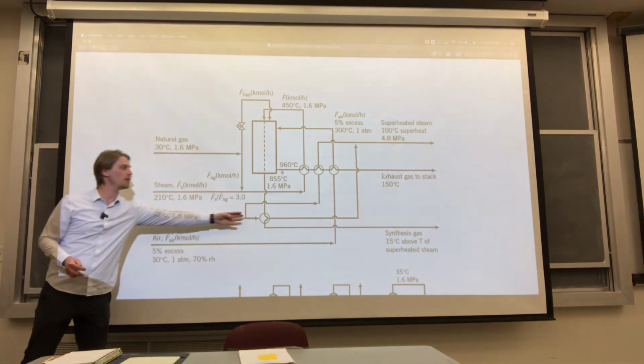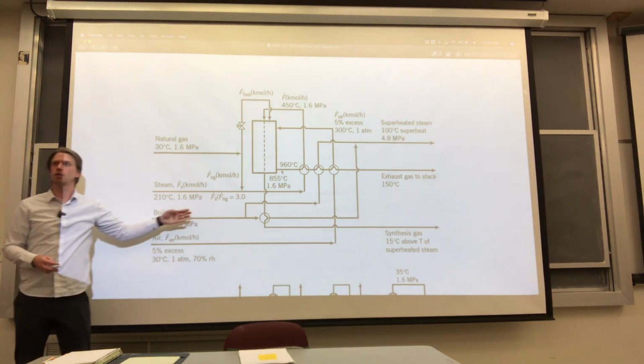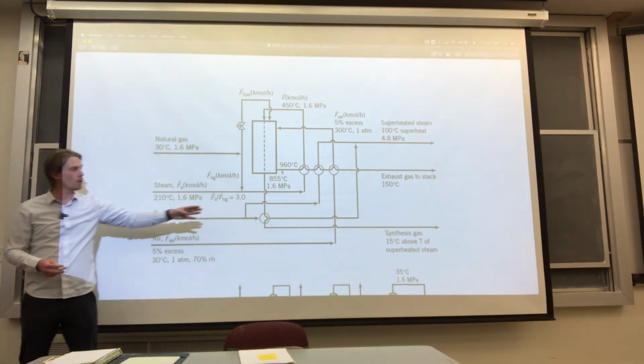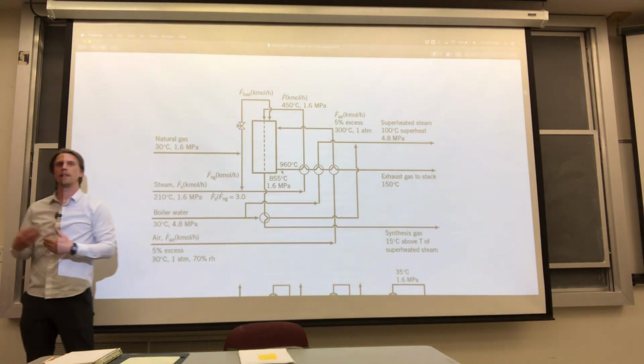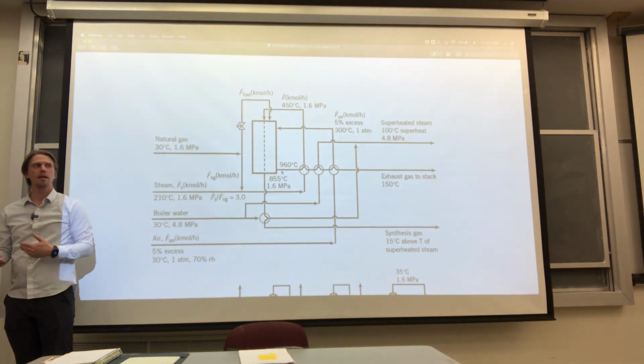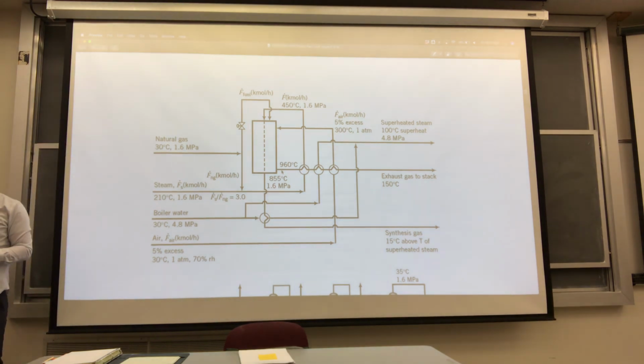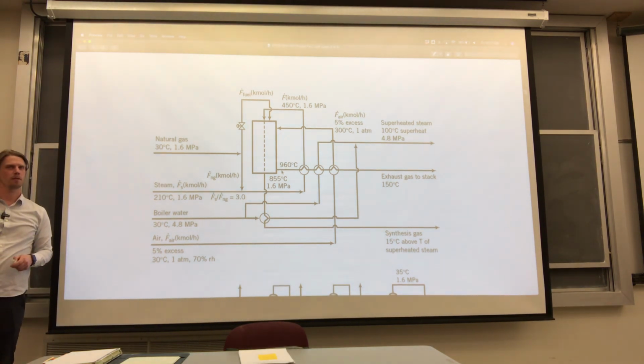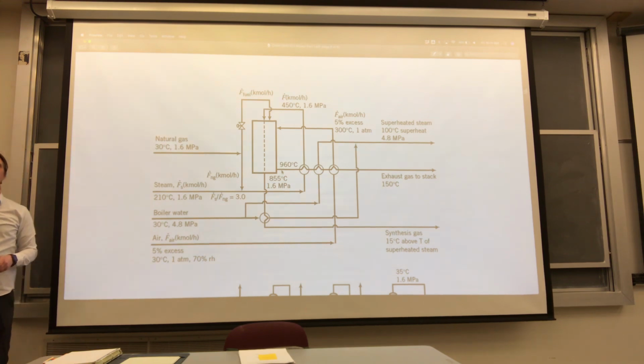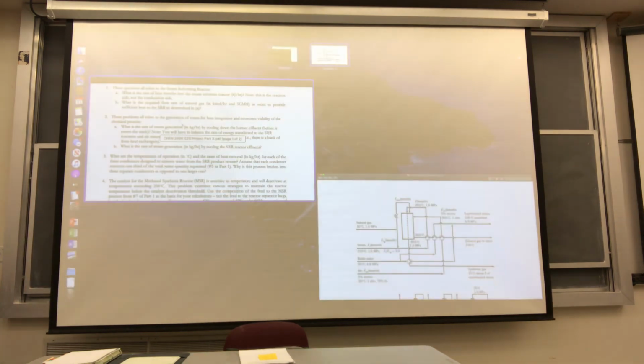The design of the heat exchanger dictates that you want to have a certain delta T. So if you want to cool this down by generating the steam, that limits that other temperature condition. And that's why these process design specifications kind of spider web out. Does that all make sense? So it's not arbitrarily convoluted. This is actually as convoluted as chemical engineers discuss things, which is fun.